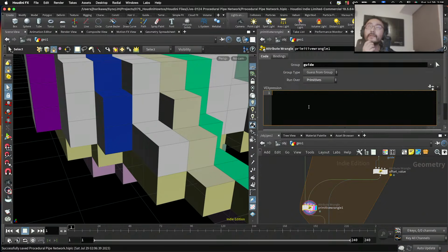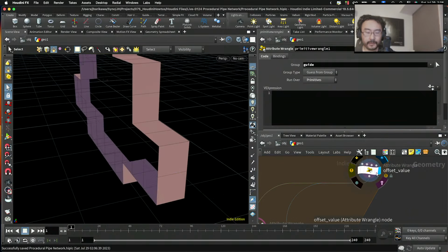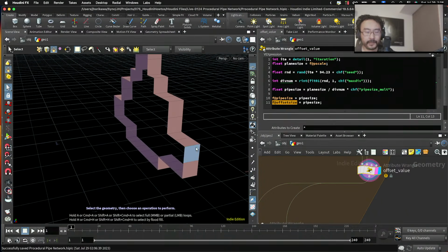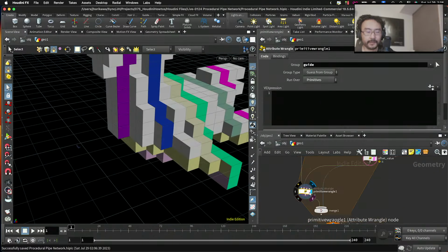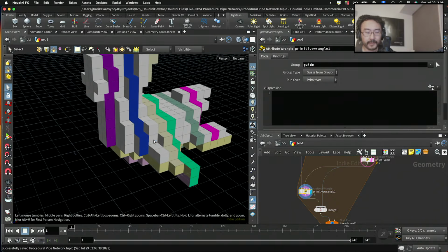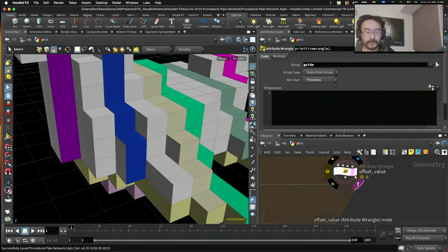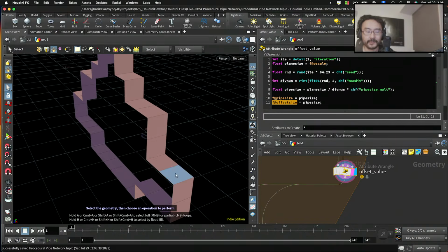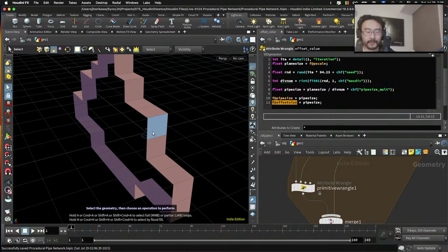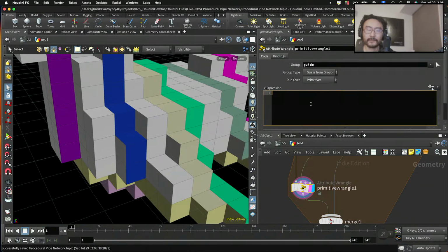Okay, now I'm going to first of all look for the same grid in the same position. So the original guide geometry has those grids, and the strip which has been created from the guide geometry has the same position. So you could get the corresponding primitive number for each strip grid by using something like XYZ distance.